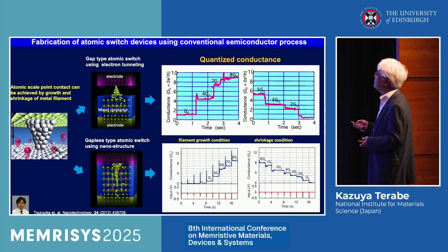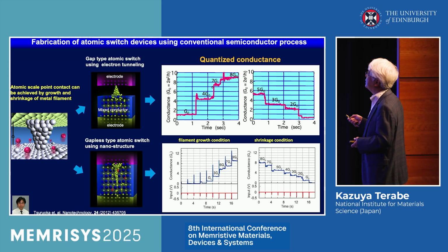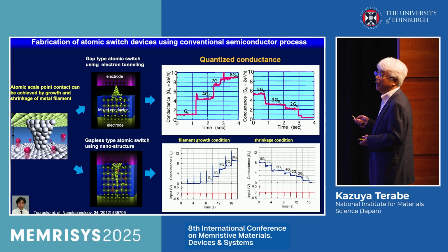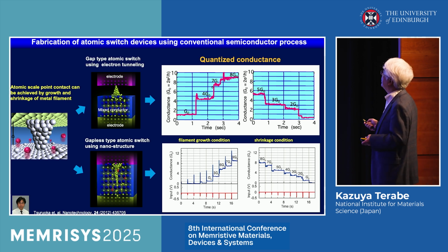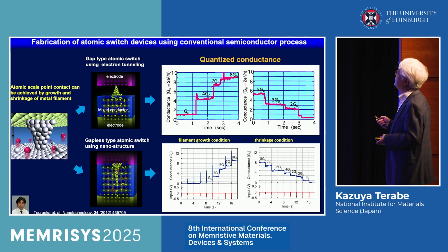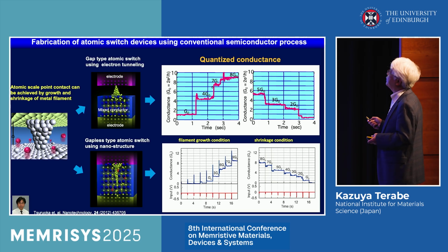This is a conductance change. Quantum conductance is observed, such a stepwise resistance change. And the polarity is changed. Resistance decreases, resistance decreases, conductance increases like this. This corresponds to the quantum conductance, in which the point of contact is formed at the atomic scale.